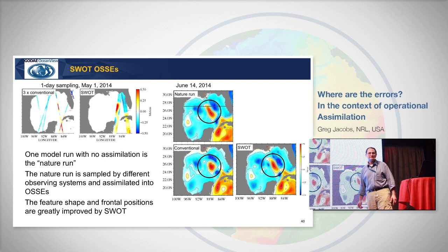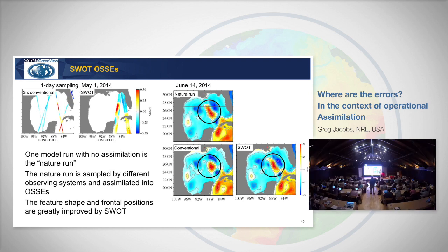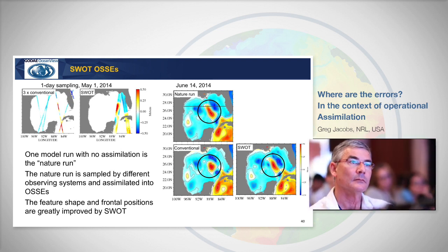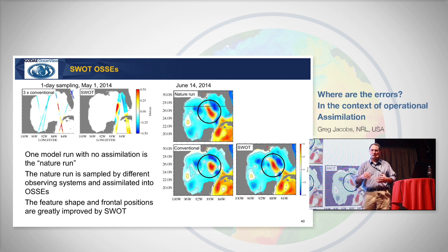Okay, something else? John? Greg, when you assimilate the drifter data, are you treating that as a time series of Eulerian velocities or something more sophisticated? No, it's that crude. We take successive positions of the drifters, and I believe the time interval used was on the order of 6 hours, and just infer velocity from those successive positions. But fortunately, they report every 15 minutes. So given the GPS positioning noise and the reporting interval, the actual inferred velocity error isn't that large, usually.